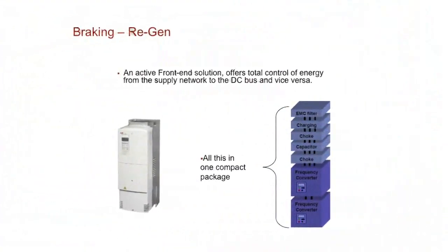So now, as you're decelerating that load, the energy is going into the drive, and then it's going into the resistor and getting burned up in the form of heat. Another way to stop the drive. And a relatively inexpensive way if you need to stop a load quickly. Resistors are not that expensive.